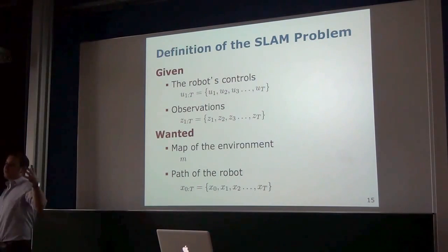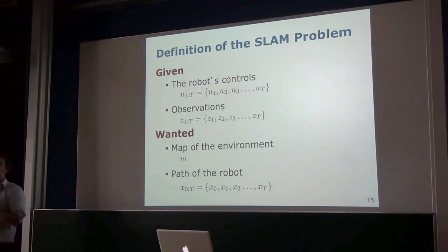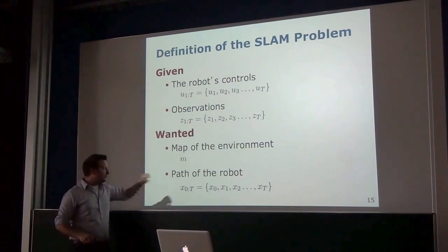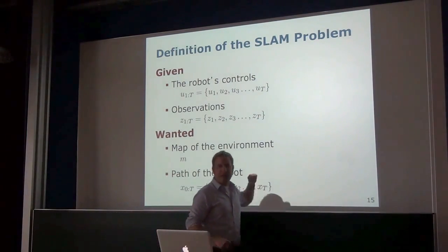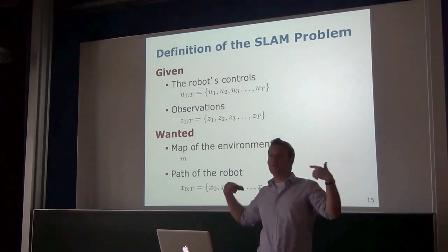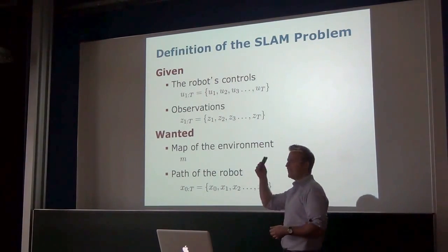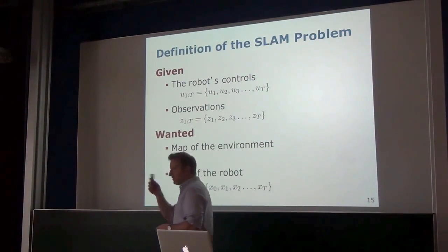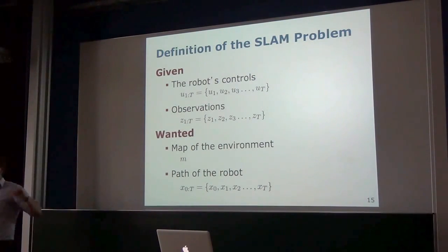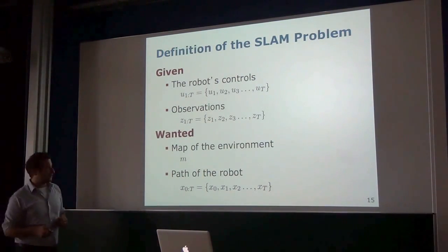Once I get a measurement, it makes sense to create a new discrete time step. Since all robots are digital systems that typically have encoders which tell us one revolution of a wheel, a second revolution, a third, I can take each of those events to create one of those discrete points in time.